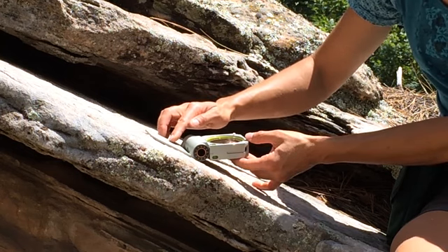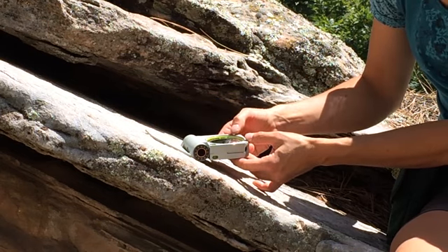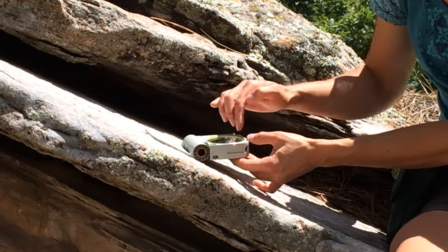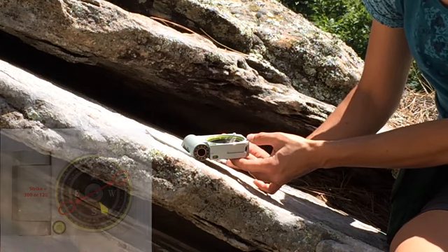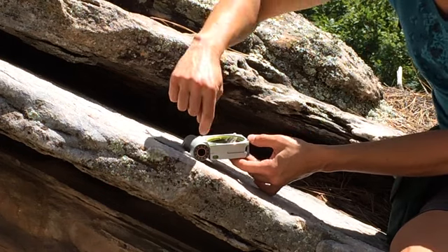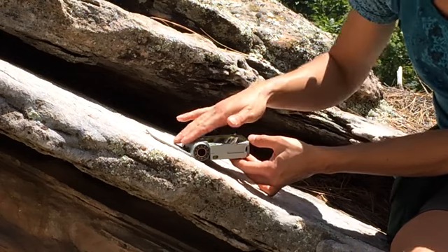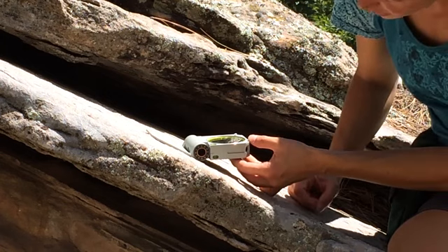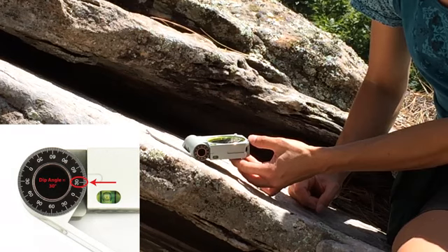So when the compass face is level, press and release the needle button 3 times to allow the magnetic needle to reset. Then strike can be read off of either end of the magnetic needle, since strike has 2 possible correct directions. Dip angle can be read on either hinge dial, but make sure that you pay attention to the lid configuration. In standard configuration like this, dip angle should be read where the hinge dial meets the top of the dip indicator. In the alternate lid configuration, read the bottom of the dip indicator.